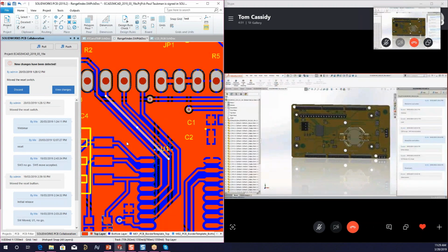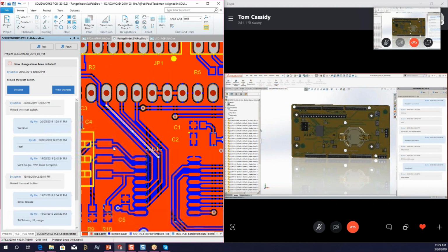Now once I push some stuff back over here, that decal will update. So it's not going to be permanently incorrect here. Once I make a change here and push it back, it will correct itself. If you do require the copper, there is a way to turn that on. So if you're doing thermal simulation, and that's something important to you, you can definitely turn that on. But for our purposes here, just having the decal gives a better understanding of where the traces are. We also have a copper pour on top of this, so just keep that in mind as well.